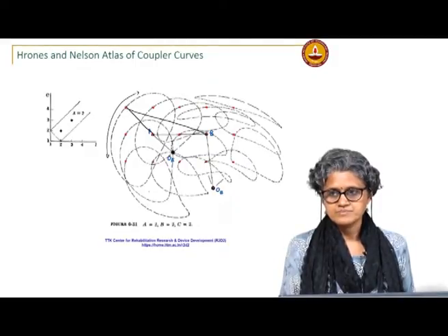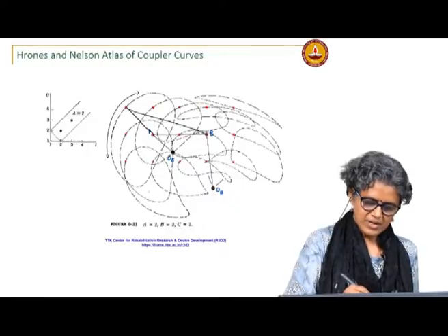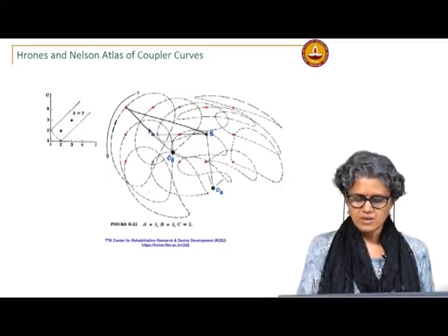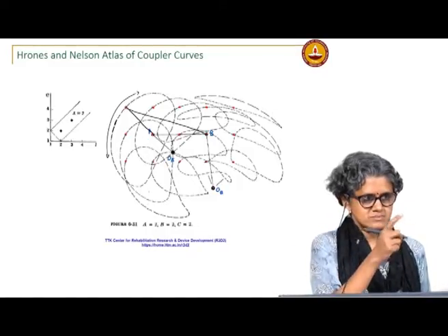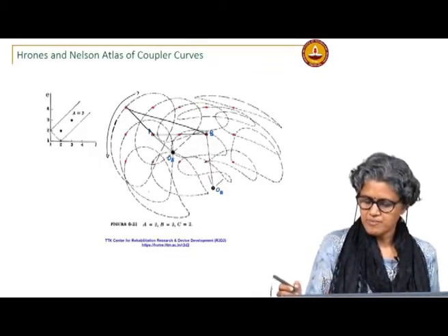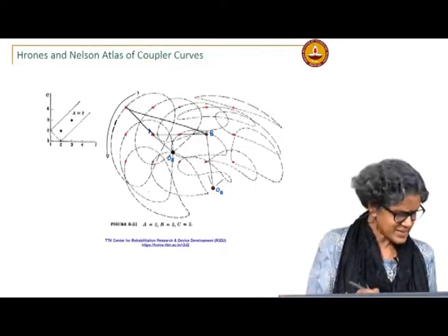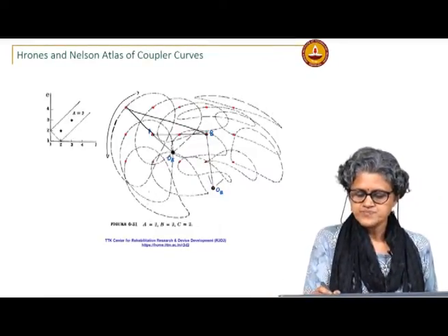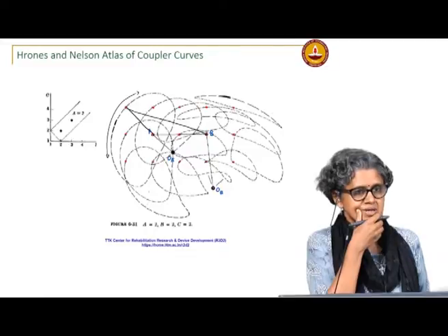Okay. And the dashes, you have these dashes that give you an indication of the crank rotations between the points. So, for equal crank rotation, I think 10 degrees, yeah. So, for every 10 degrees of crank rotation, this would be the distance traversed by the coupler point.